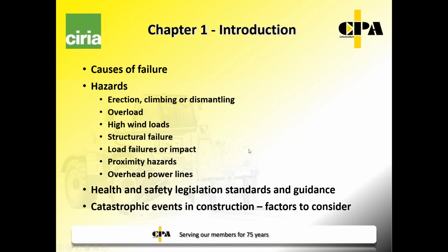And then the last hazard we have is overhead power lines, which fairly obviously, if you get the crane too near an overhead power line, or you get the load suspended from the crane too near a power line, then you will get arcing across, and then there is a risk of electric shock danger to the operator and people in the vicinity.